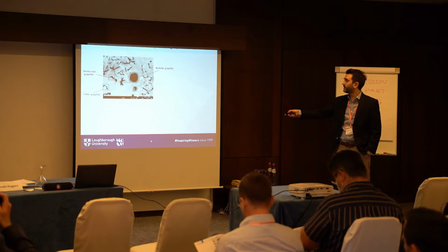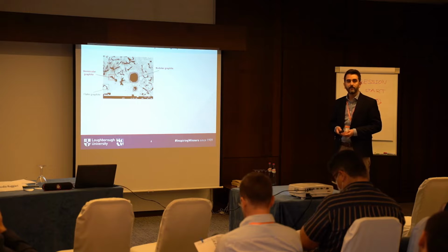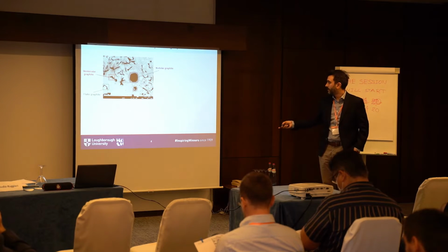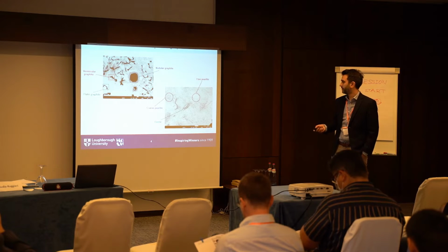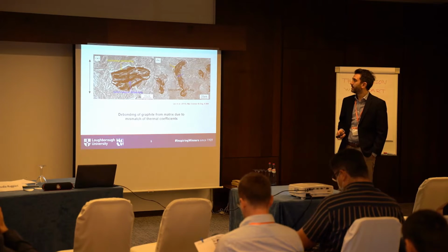If you only have this nice sphere, it's called spherical graphite iron, or ductile iron. There are plenty of studies on that one. To make it a bit more complicated, if you etch your specimens and do your scans again, you see ferrite, and maybe pearlite, in the forms of fine and coarse pearlite.